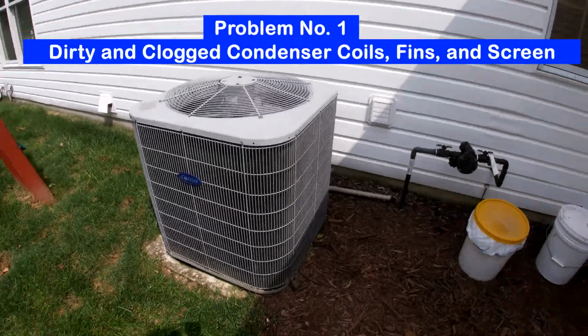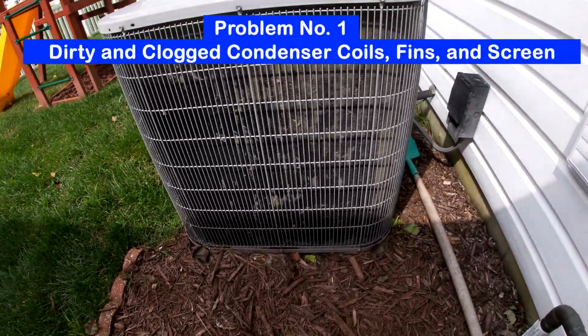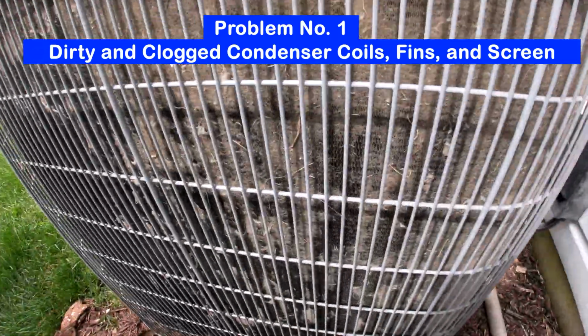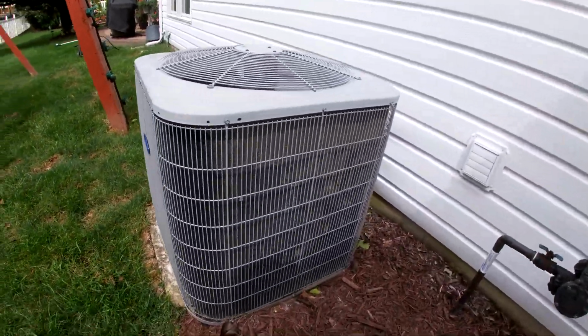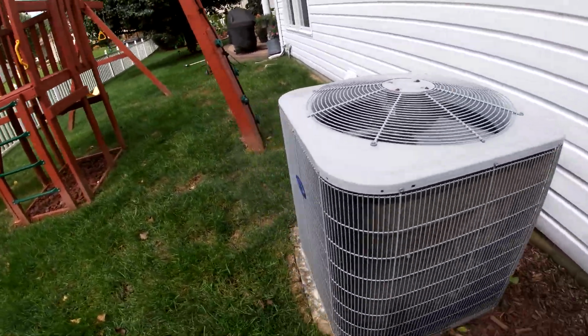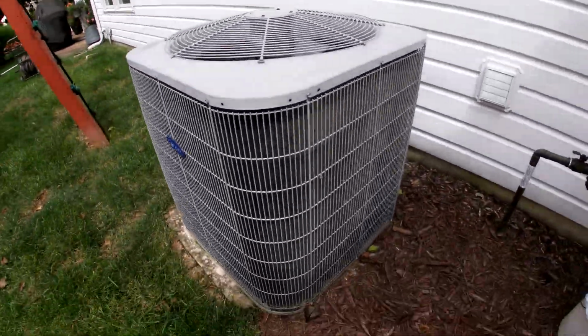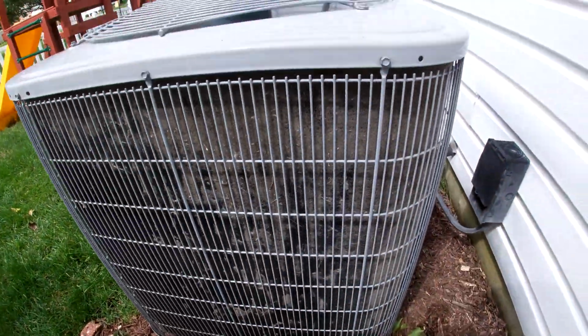In my opinion, this is the most common air conditioning problem that you will encounter. As you can see, my condenser and its coils, fins, and screen are clogged with dirt, debris, bird feathers, and other stuff. In this area, the condenser is experiencing major restrictions of cooling airflow. In fact, I've already experienced this problem twice this year. I thoroughly cleaned the condenser in late May, and it's now mid-August and it's starting to clog up again.